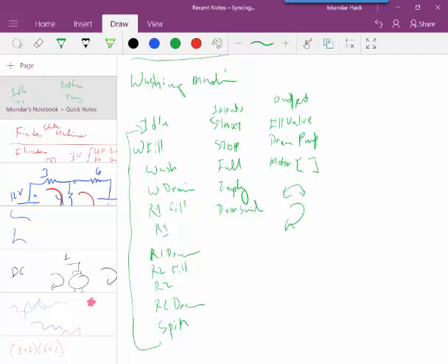So, again, if you were to do this, then you'd have to do a state transition. I can go from wash, fill, back to idle if I hit, and I'm going to put another button here, I'm going to call it abort. The stop button just stops it from what it's doing for right now, so that you can open the door. The abort button drains the machine, and it just stops the operation, so you can put more clothes in or whatever. So I'm going to put an abort button on this one here.